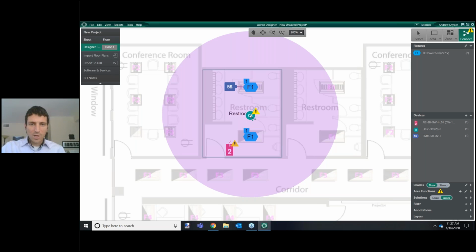Now I wire up my occupancy sensor, and I say wire with quotation marks around it. This is a wireless connection, so you'll see a dotted line instead of a hard, solid line. And last but not least, I'll associate my Pico remote with a wireless connection as well. I've now completed my restroom. So now that step 5 is completed,